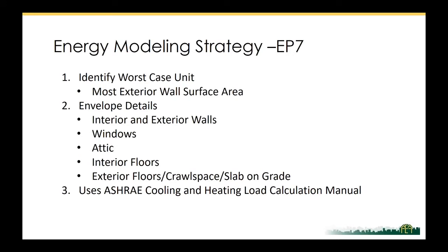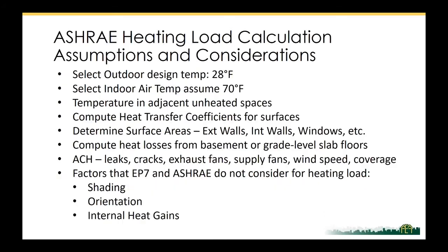We also wanted to make sure that we had the most southern exposure to windows, which Energy Pro 7 doesn't take into account. And this kind of goes for all modeling or all calculations: we want the envelope details, interior and exterior walls, windows, attic, interior floors, exterior floors, crawl space, slab on grade. And the energy modeling software EP7 uses the ASHRAE cooling and heating load calculation manual.